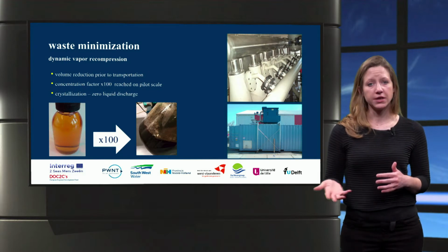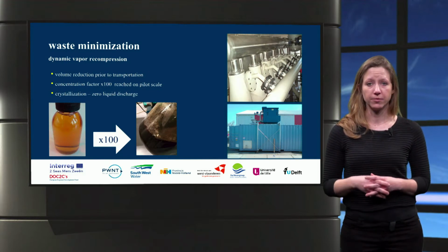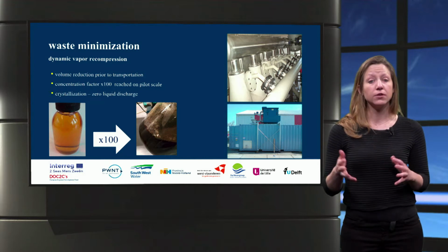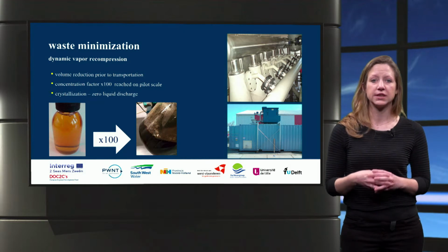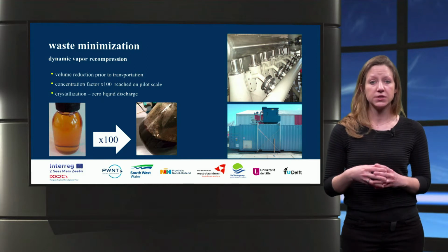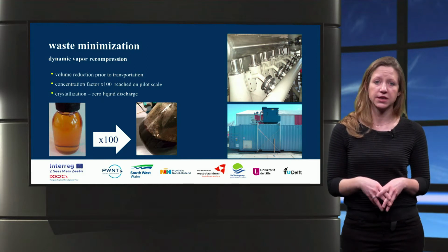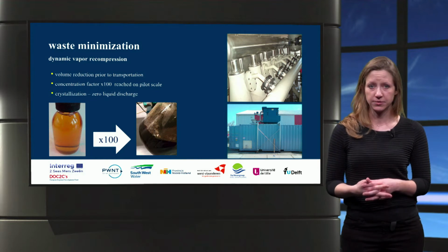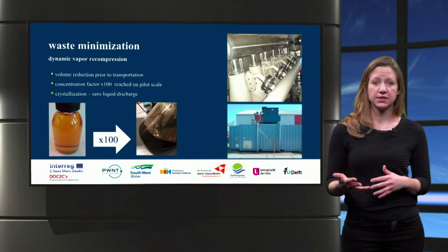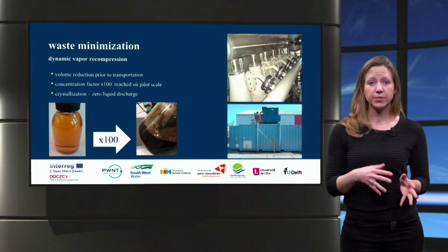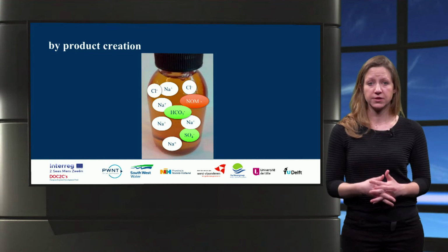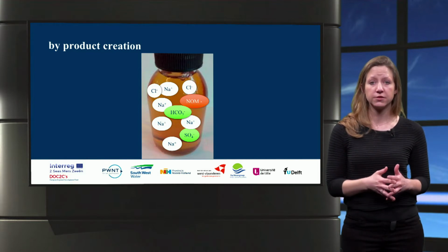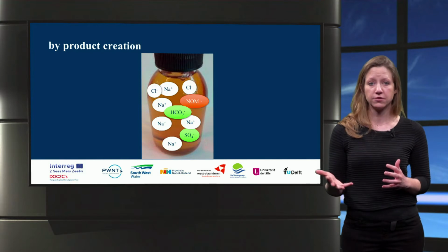A second usual strategy with brine treatment is to reduce the volume to a minimum prior to transportation, for example, even all the way to zero liquid discharge. The evaporation technique called dynamic vapor recompression was designed to deal with salt concentrations way above crystallization levels. It was tested here successfully, reaching on pilot scale concentration factors up to 100 times. To increase the operational efficiency of dynamic vapor recompression, it can be combined with nanofiltration. A last possible strategy with brine treatment is to achieve the full separation of the major salts and the organics toward the creation of byproducts.